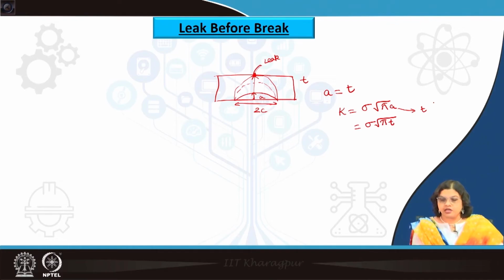When we use a material for any kind of design, we first of all need to know its fracture toughness value, and this means the plane strain fracture toughness value, which is supposed to be a constant one. Now, in practice, we also need to figure out what the fracture toughness values would be under certain conditions, and whether that exceeds or is less than the predicted value determined for different conditions.